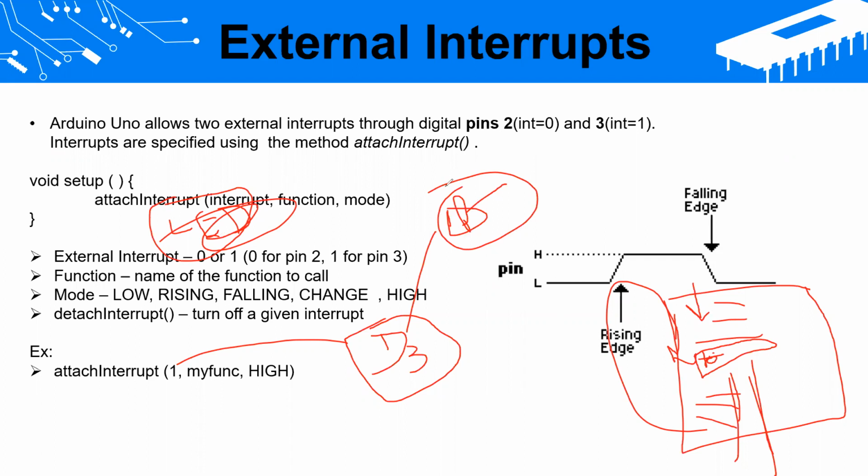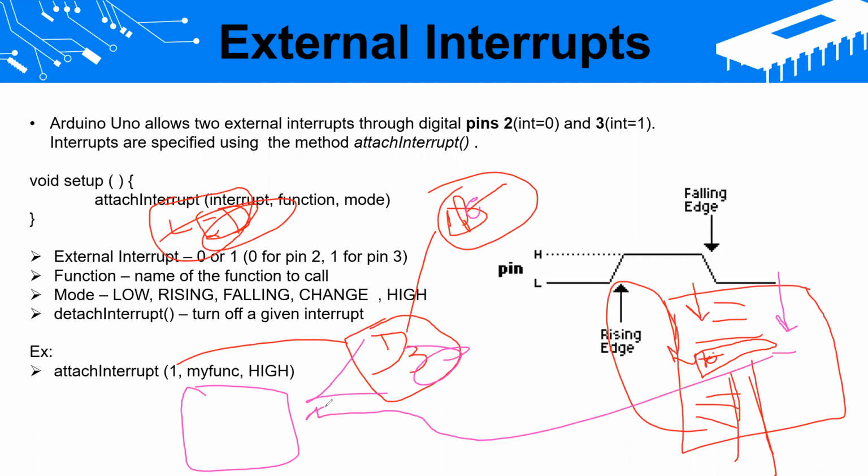But that is the illusion we're going to develop. The interrupt is at the hardware level, so we are putting this external interrupt, and I'm putting that piece of code to light up the LED. The main code executes normally. If I press this push button, the hardware will detect that I'm getting high voltage, stop the execution at this point, and redirect to this point. Then it lights up the LED, and when it's done, it comes back to this place.